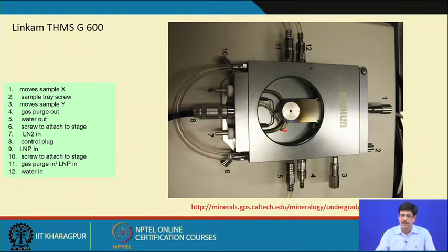And the advantage of this particular Linkam stage is that the temperature at any point of time can be held by the controller exactly at that value, irrespective of whether it is below 0 or above 0. And these kinds of stages can also be calibrated by using synthetic fluid inclusion standards or any other standard material whose melting points are known, and it works on a 3-point calibration below 0 degrees Celsius, at 0 degree, or any temperature higher.